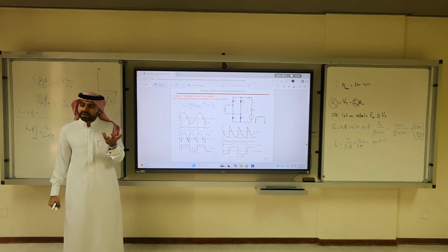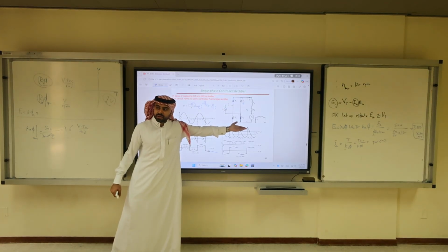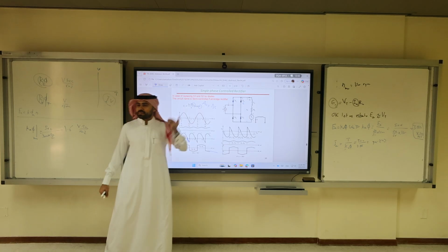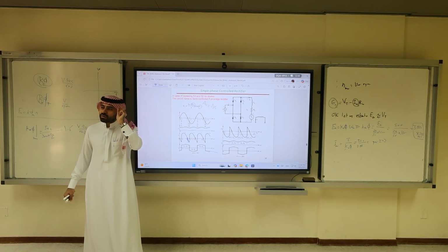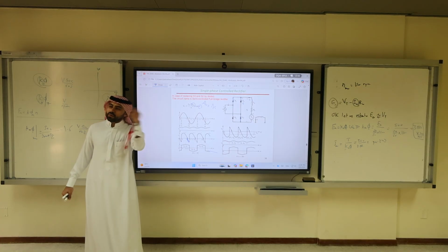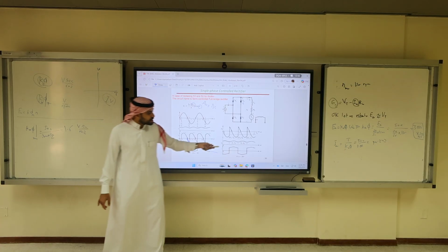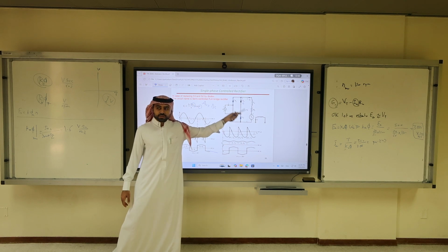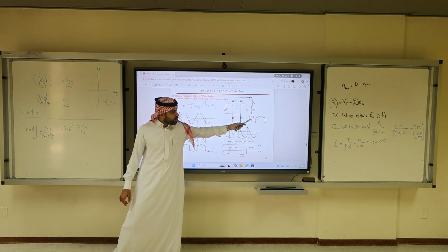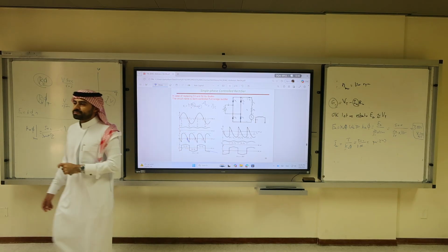It means we are sending power from DC to the supply. And this is one way to think about how regenerative braking sends the power back to the battery or to the supply. Do you see that because here the power is negative, it means this movement of the DC machine would generate the power back to the supply?